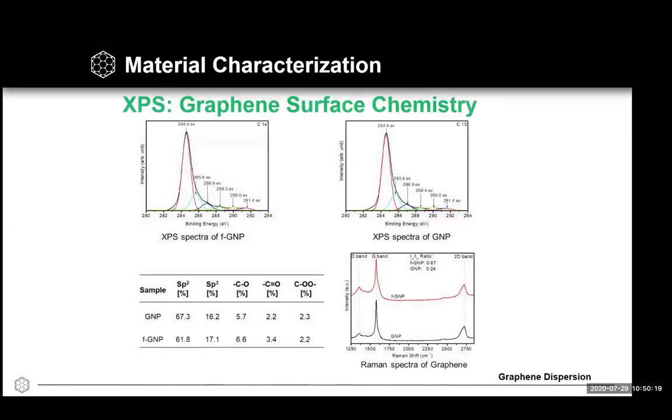characterization of the material. The other technique we use is XPS, which is also a good technique to characterize the surface chemistry. For example, if you want to see what is making a change in the hexagonal benzene ring, if we are converting during our process, doing any chemical treatment, introducing any functionality, or changing that sp2 hybridization to sp3 hybridization.